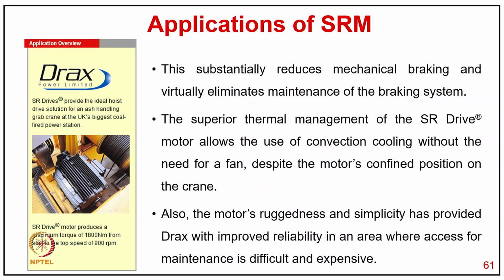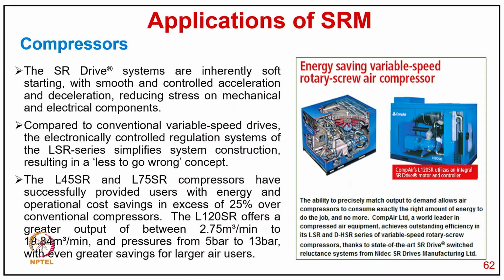This substantially reduces wear on the mechanical braking and virtually eliminates the maintenance of the braking system. The superior thermal management of the SR drive motor allows the use of convection cooling without the need for a fan, despite the motor's confined position on the crane. Also, the motor's ruggedness and simplicity have provided improved reliability in an area where access for maintenance is difficult and expensive.